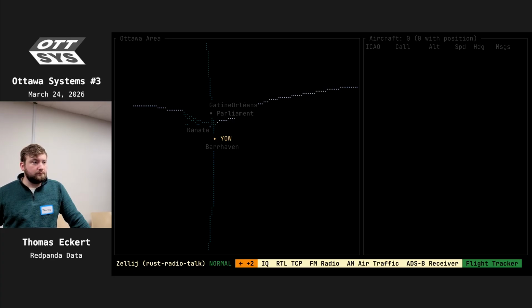Whereas in frequency modulation, you have a base carrier frequency of, let's say, 5 hertz or whatever, and then you're actually changing it from 5 hertz to 5.5 hertz, so it's oscillating faster to encode the audio, and oscillating slower around that frequency. So that is the core difference. But in all cases, you do have the base frequency of the thing. And depending on how powerful your transmission tower is, that determines how far your wave goes.